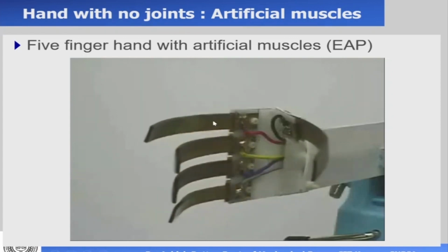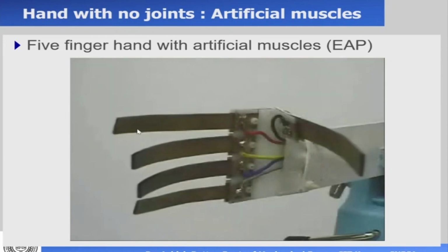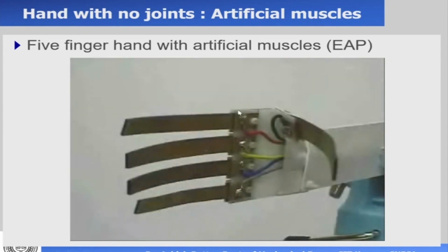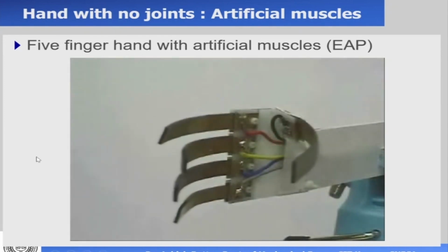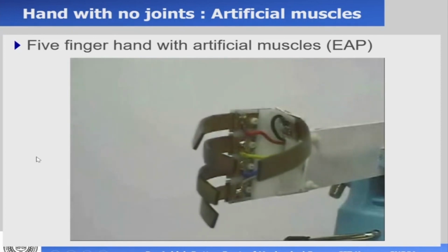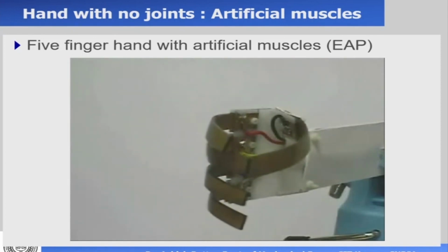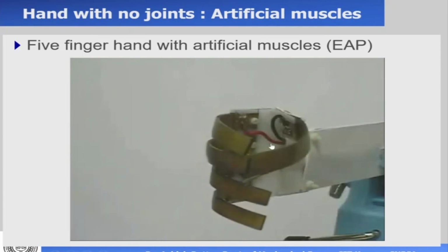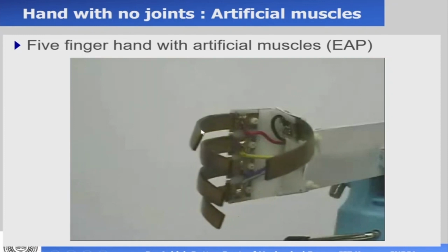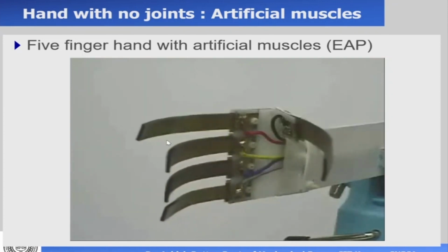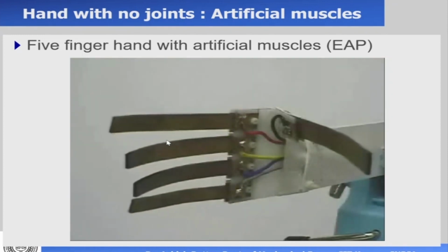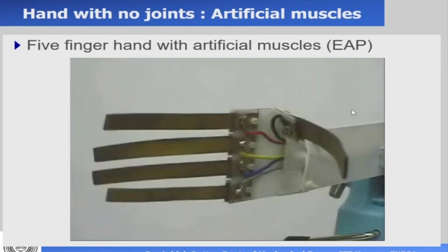Okay, so this material is electroactive polymer. It's Nafion here. By applying a voltage in a particular direction, we can make it bend in a particular way. Okay, if you reverse the voltage, it will bend backwards. Now this is independent of the size effect, which means that if you cut this, you can make a very small robot which will behave like this, and it has nothing to do with the size because there is no DC motor there. So all the micro and the nano applications normally use smart actuators for actuation. We'll come to part of this when we talk about sensors.